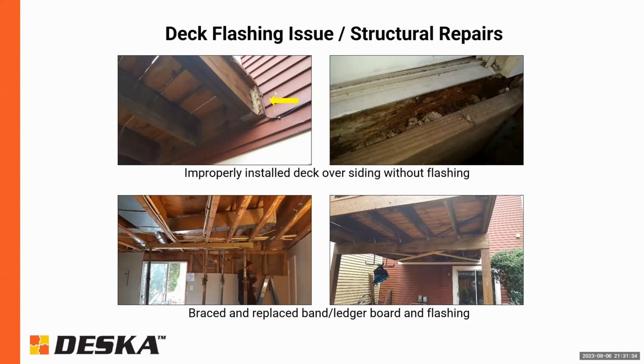And you're solely relying on these bolts, which are essentially loose, and it's not appropriately supported at all. Water gets behind, rots the band board, rots the interior wall out, causes a lot of damage, typically very slowly. So anytime you see a situation like this, or if you just see there's no flashing, I would recommend putting a moisture meter on the drywall in the interior. We've seen situations where the entire wall has essentially deteriorated, and no one knew about it until after 30 years, they're beginning to see a little bit of mold or a little bit of dark staining on the wall.